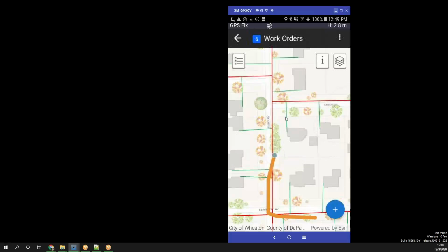So not only do we have a physical or visible proof of where we were, but we store this breadcrumb file as a CSV file as an attachment. For every point, it drops a lat long value in the file, as well as whatever the corresponding reading was from the DPIR device at that time. So here I am tracking my leak survey.